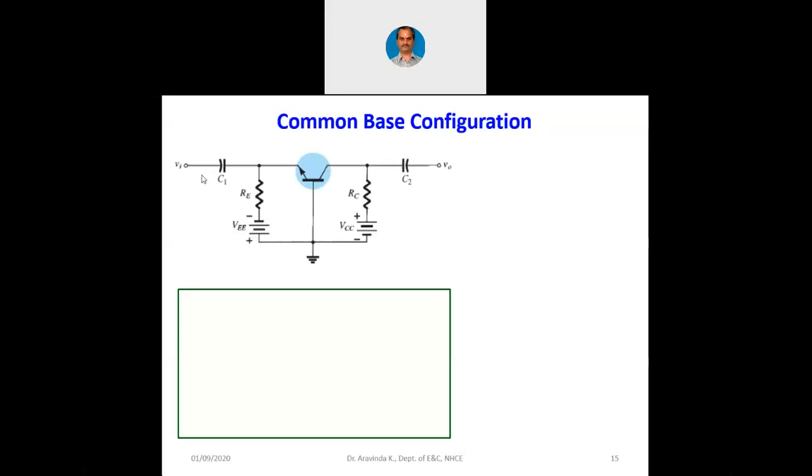Now as per the AC signal, the transistor switching is going to be slightly affected. From the middle of the Q point, it will slightly switch towards the saturation side or towards the cutoff region side, and that is when at the output also we will have a swing in the collector current. That is how this switching configuration is working. When you start working in the labs, you will actually measure the Q point, and when you work with the amplifier circuits, you will understand these concepts more clearly.